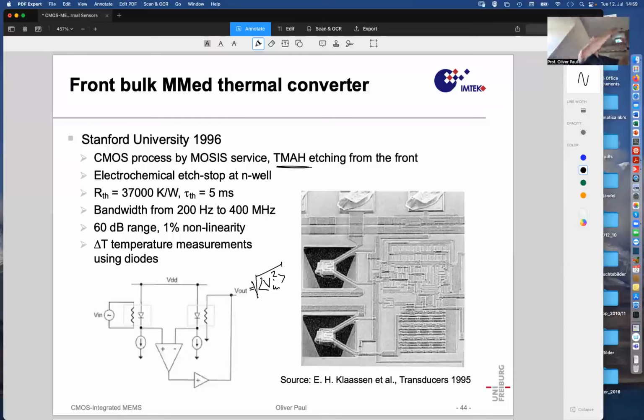The etching stops there naturally because the electrochemical charge transfer can't operate anymore, because the voltage prevents that. So that also works here. While etching, they had the contact to the N well under potential, and then this was spared from etching.